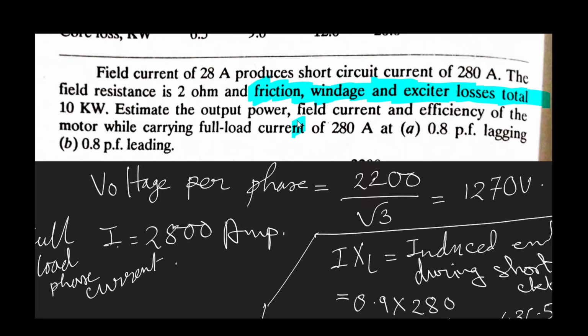So, what type of current flows out of the machine in generating mode, or into the machine in motoring mode, all depends on how much drop we get across our synchronous impedance. Now, as soon as our E takes a different value, the core loss will also change in accordance with E, not with V.